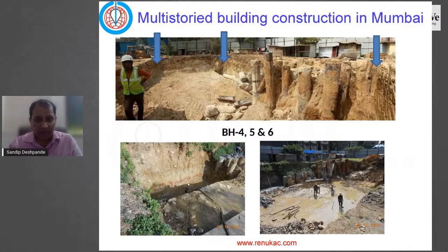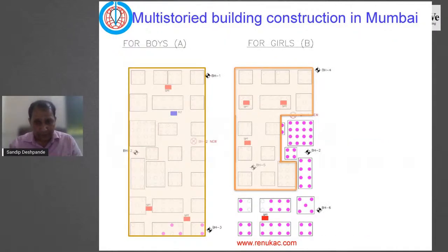So no basements were proposed. They had to build up the building from the bottom to the top, build up the foundations, and take it forward. So finally, it was decided that, being a government project, whatever pile foundations are completed, you adopt the pile foundations and integrate them by considering a raft foundation at the founding level and construct further. So this was the kind of final output for foundations.